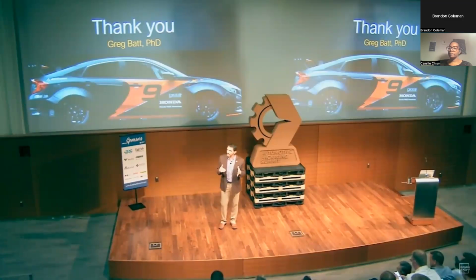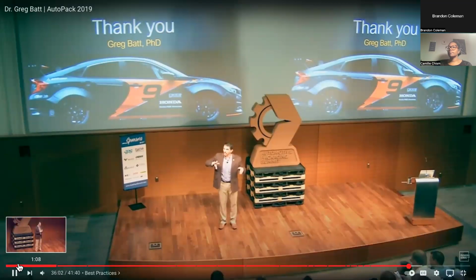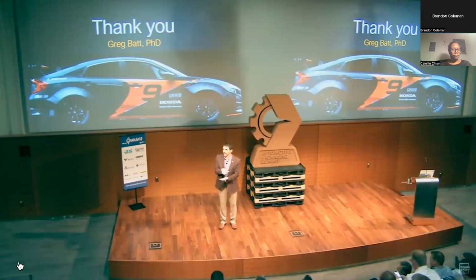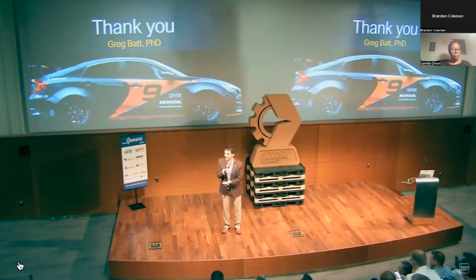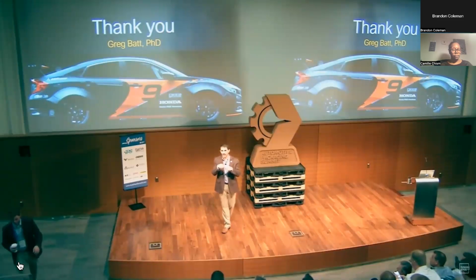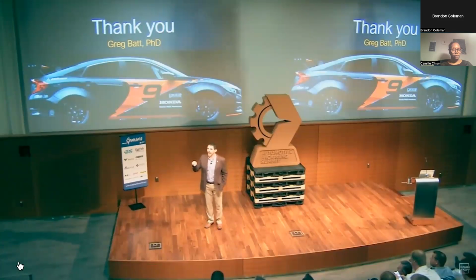And I mentioned the time compression: they will increase the intensity of that profile to decrease the test time. And that works, much like you could cook your cake a little faster if you increase the temperature. But if you increase it too much, you burn the cake and everything inside doesn't get cooked. That same thing can happen in package testing: we burn the cake.